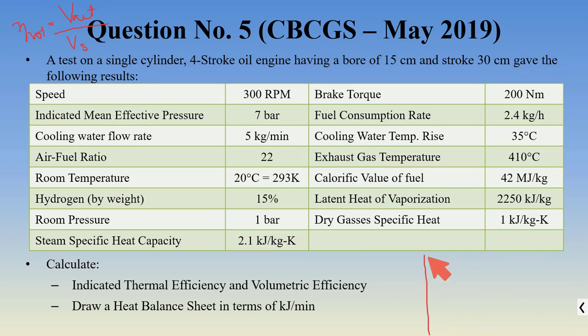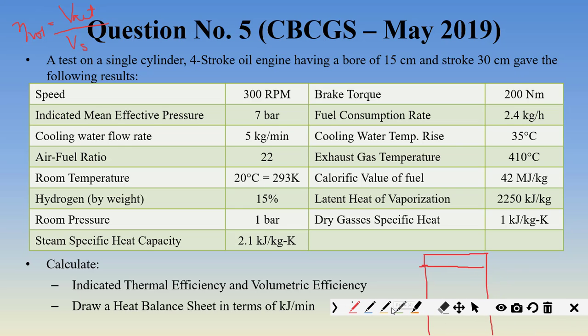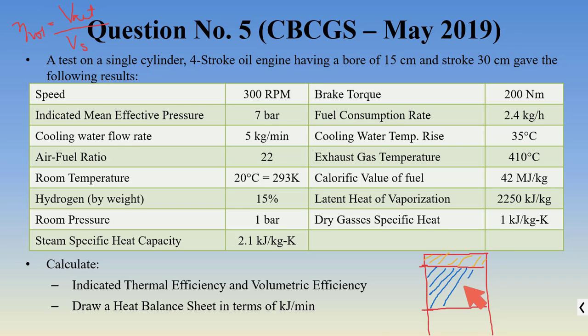Okay, to see this, if this is your cylinder, this is your top dead center, this is your bottom dead center, right? Above the top dead center, what do you have? Above the top dead center is your clearance volume, right? This is my clearance volume. What is between top dead center and bottom dead center? This is my swept volume. So ideally what should happen? When the intake valve opens, all the intake air should come in and fill this entire volume during the intake stroke.